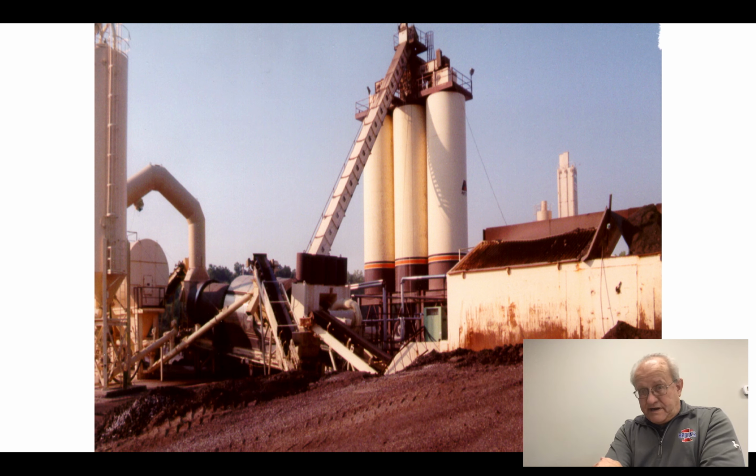The 3 large round things are just storage silos. Completed mix goes up the drag slat, the big square thing, it's just nothing more than exactly what it is, a drag slat. The mix comes out of the drum into the boot of that thing, big chains with slats on it. It just drags the material up and you deposit it into the correct silo.